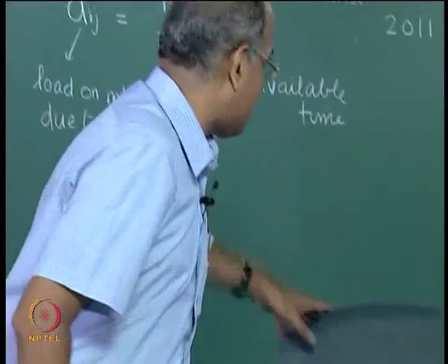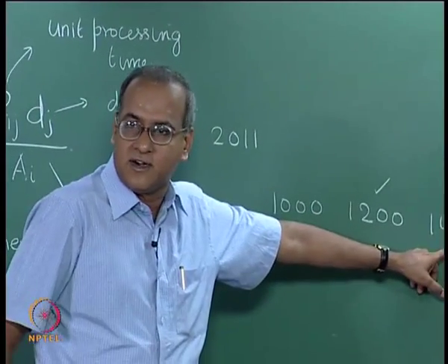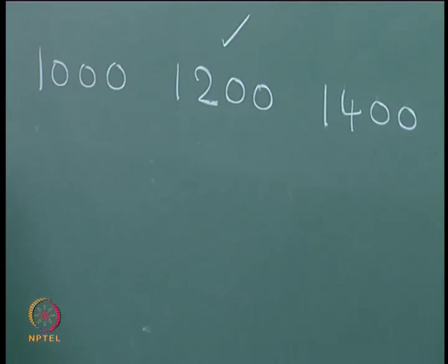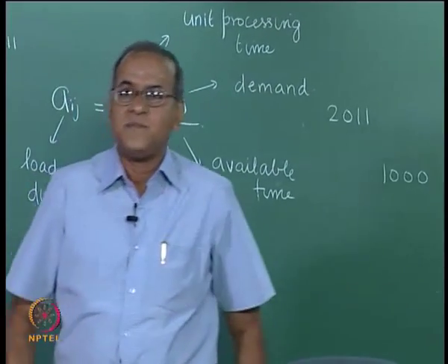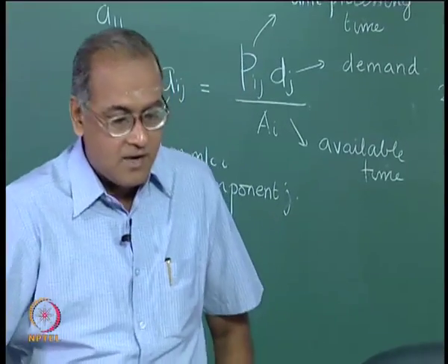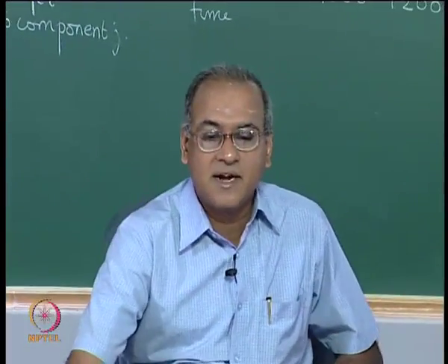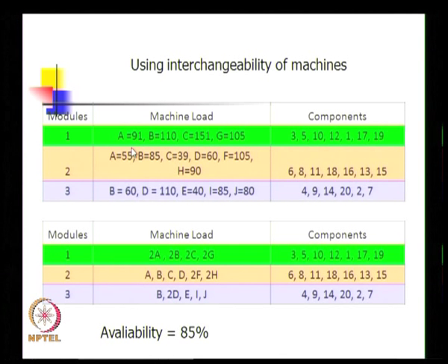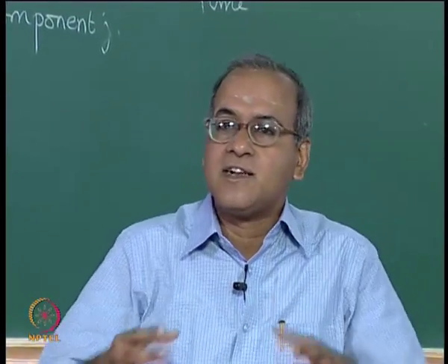Now as the age of the cell increases and we move into the third year, the workload will not be this 1200, but the workload will be 1400. Therefore the 146 that we calculated using the 1200 will be more than 146, let us say it will be 160. Now this 146, which is split as 91 and 55 here, can become 110 and 60 to get 170. So suddenly we realize that the same cell which did not have that much requirement now has more requirement. At the same time we also understand that we cannot change the cell configuration.